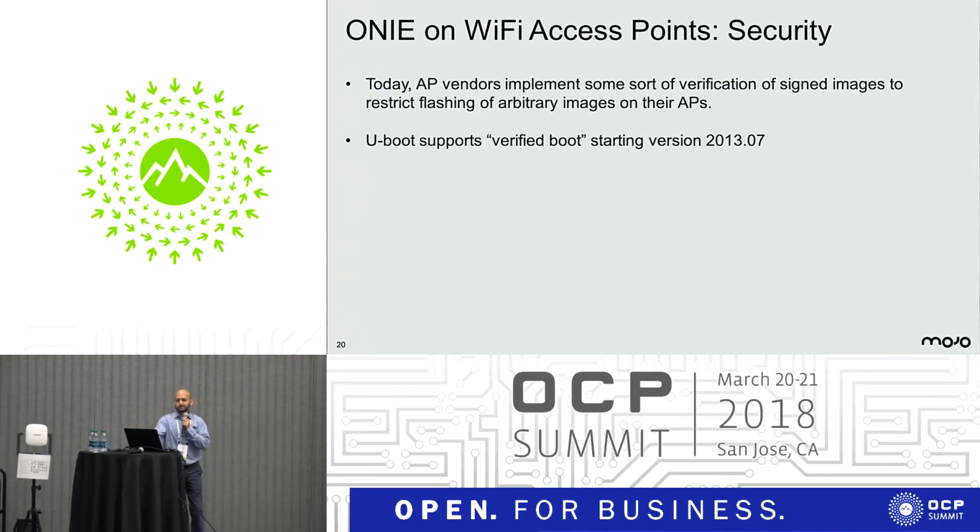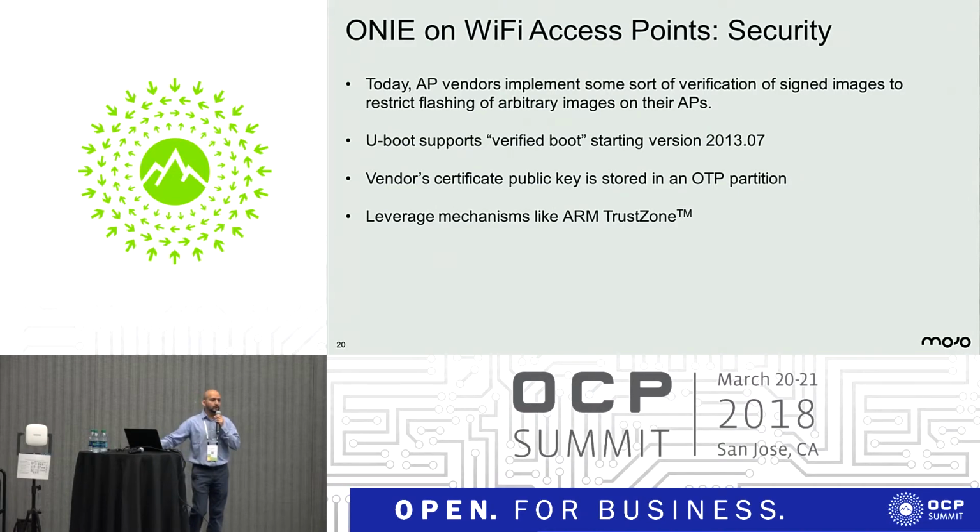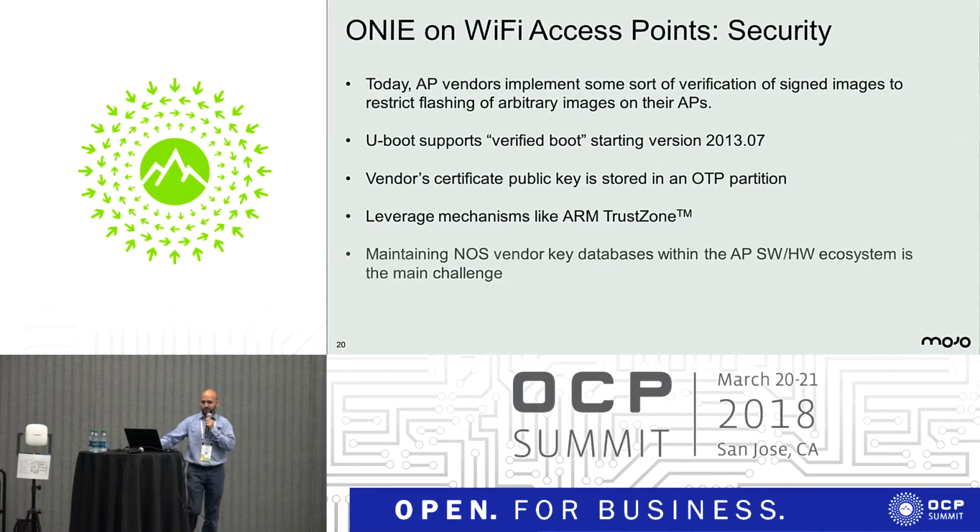U-Boot has supported verified boot starting with the 2013-07 version. So it allows you to make sure that your kernel is signed with the right key and things like that. And then the AP vendors typically store their keys in some kind of one-time programmable memory, so that it cannot be altered. There are also possibilities of leveraging mechanisms like ARM TrustZone, etc., to further solidify this secure boot process.